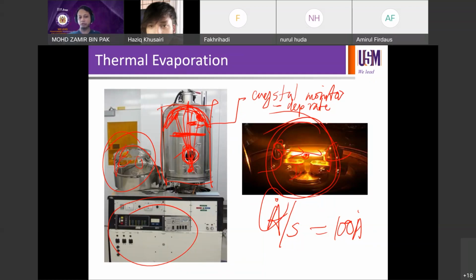Dia akan in fact tell you the current thickness pun. For example, as you go during the process, you probably see now it's like 23 angstrom is being deposited, ataupun 2.3 nanometer lah. Okay, so that will increase over time. So you can get to see when do you need to stop, if you run the system manually. Kalau dalam mass production, it's all defined in the recipe already.